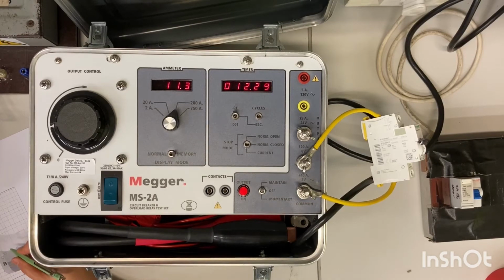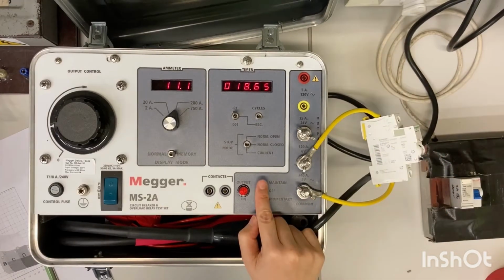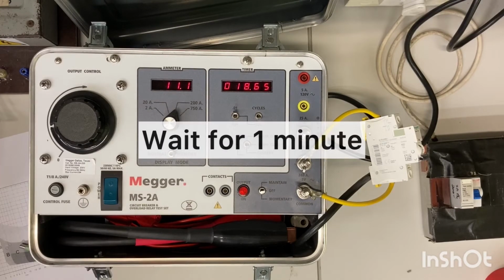So we just wait until the MCB trips. We just heard the click sound. It means that the MCB has been tripped. We should press the button to the off position. The display shows the current and the disconnection time, 18.65 seconds. You have to record down this set of data.